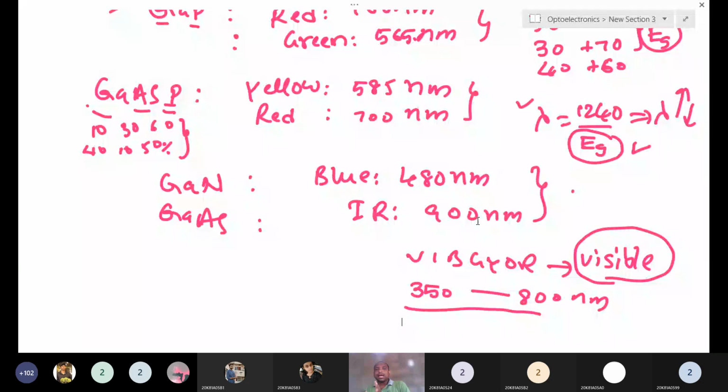At the interface or space charge region, the electron and hole recombine. Once they recombine, it will emit a photon, that means it emits light. This light color will depend on the material. Different materials have different band gaps. We estimate the wavelength of the material as 1240 by the band gap of the material. Using this estimation of wavelength, we can choose different materials depending on our requirement. This is the way of emitting different color light from the LED lamp.